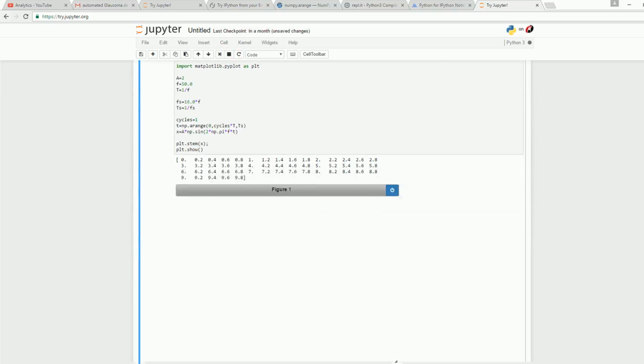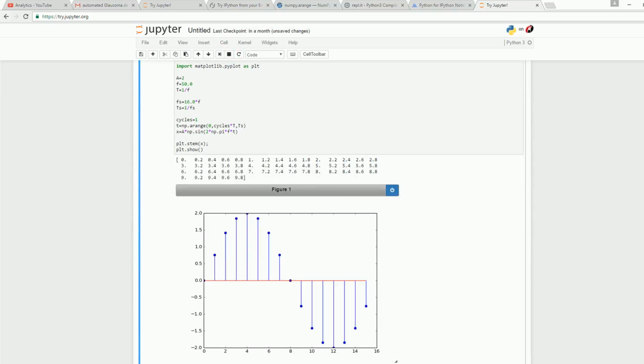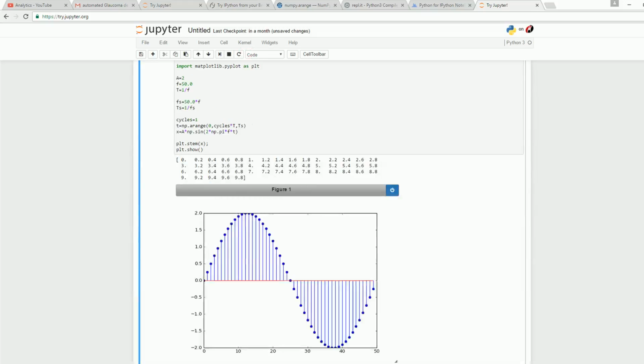you'll have many more samples which are going to represent the signal. But you still have an approximation over here. As you keep on increasing the sampling rate, say make it 50. Earlier you had totally 16 samples, counting 1, 2, 3, up to 16. Now if I make it 50, you'll have 50 samples, okay, with these errors.